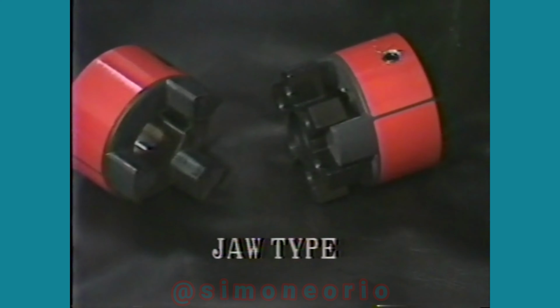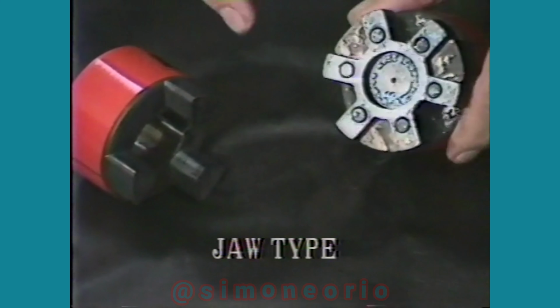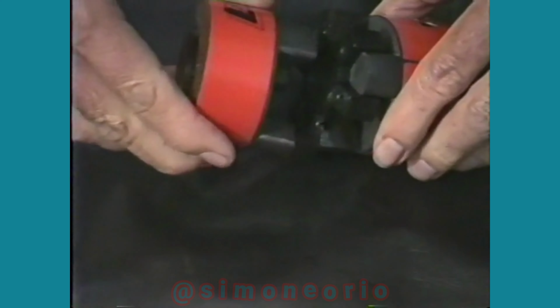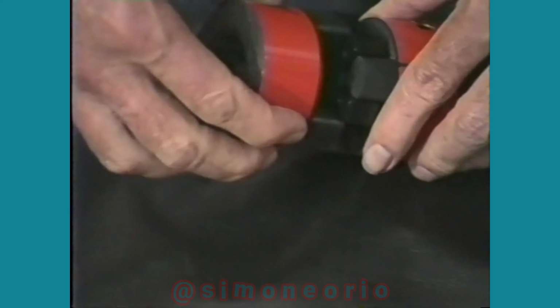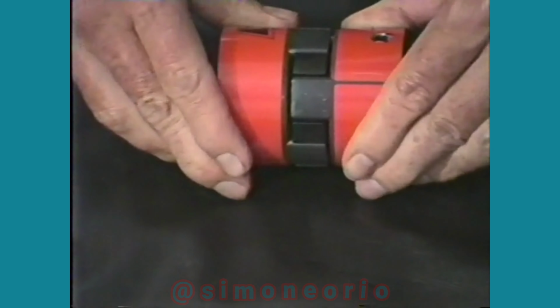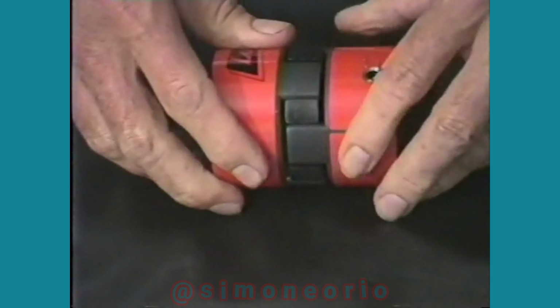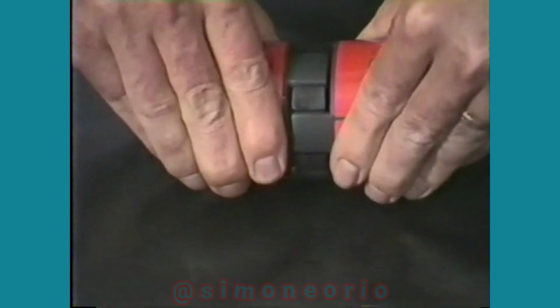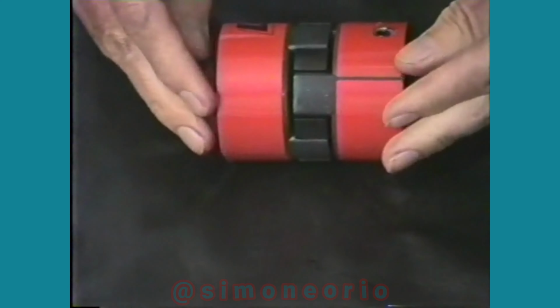Here is the jaw type coupling. This part is called the spider. The spider fits between the 2 jaw hubs like this. Spiders are made from various materials. As can be seen, the 2 halves flex in relation to each other. If soft material is used for the spider, the coupling has the ability to dampen vibration and shock.